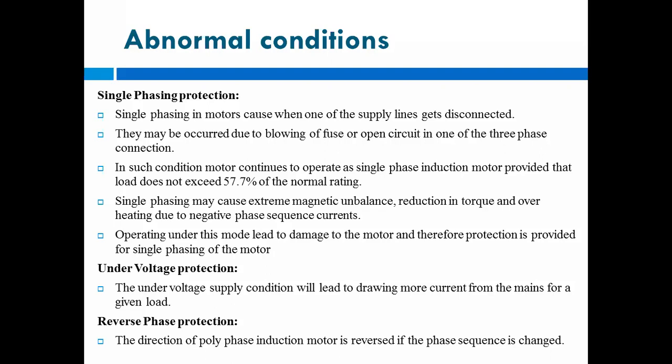So this single phasing may cause extreme magnetic unbalance, reduction in torque, and overheating due to negative sequence currents. Okay, so extreme magnetic unbalance is there, then the torque is reduced, and there is overheating due to negative phase sequence currents, because there is unbalance between the phases.